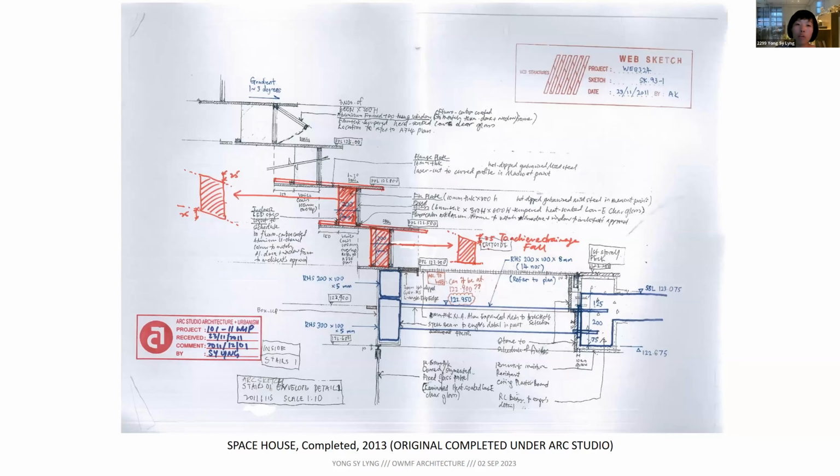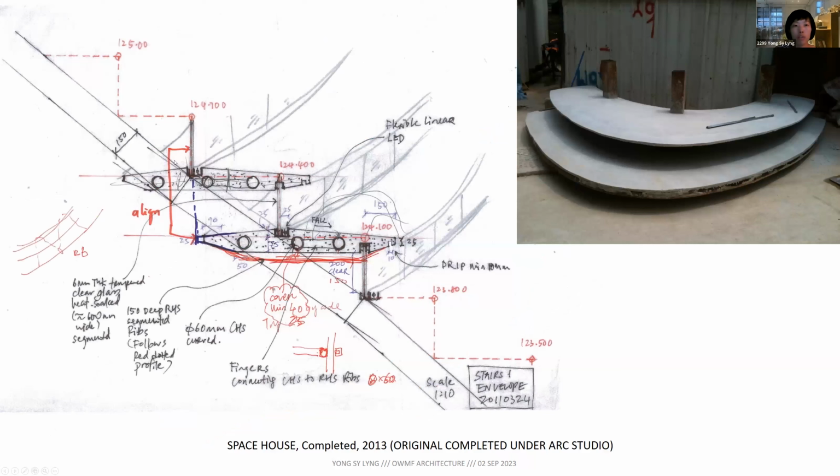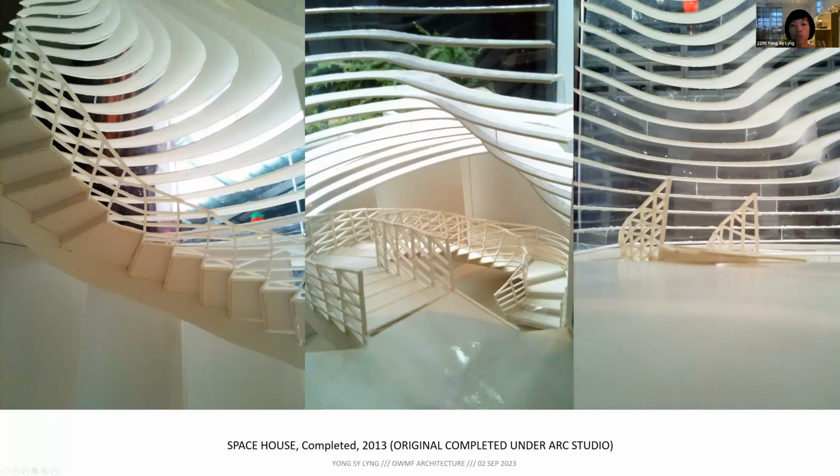Then of course we had a very, very good structure engineer, Web Structures. And this is the detail that we have. And for the water to flow, actually every vertical element has to be slightly slanted so that the water will flow outwards. Okay, before that, you see all these vertical elements. Another thing that we are quite sure we don't want after this mock-up is these 5 very heavy beams or ribs supporting this whole thing, right? We don't want 1, 2, 3, 4, 5 stringers.